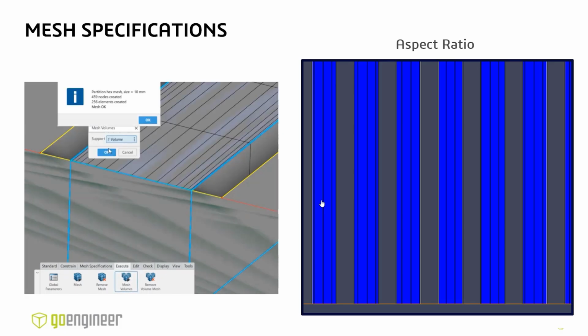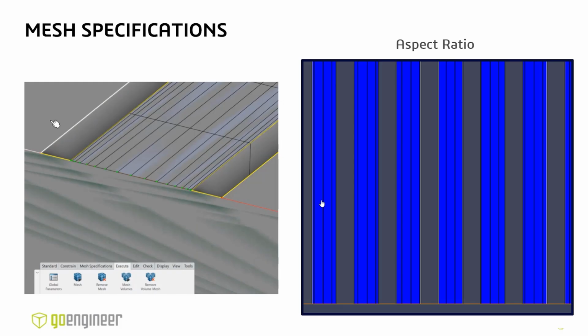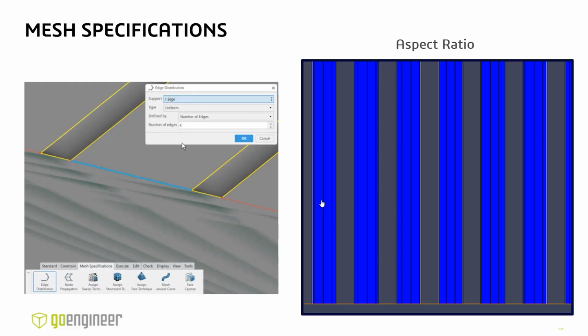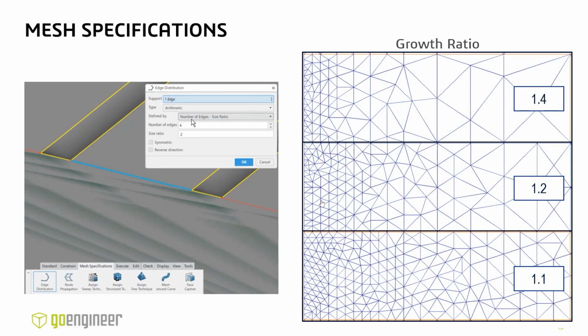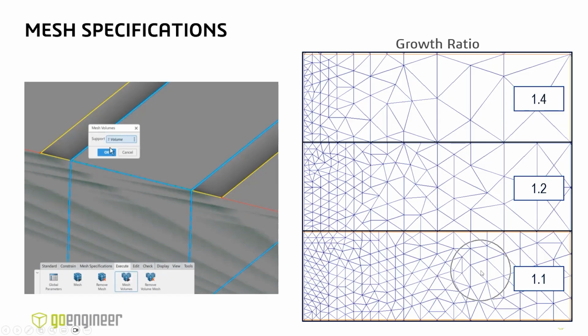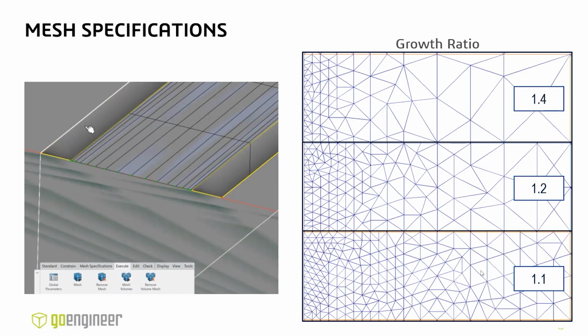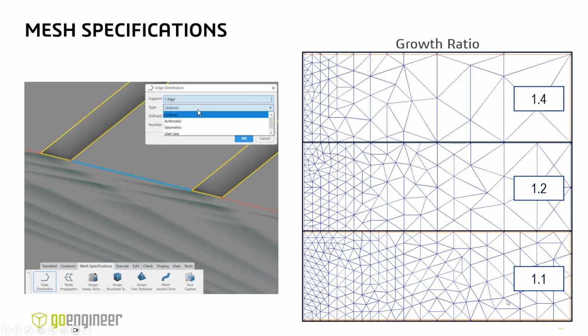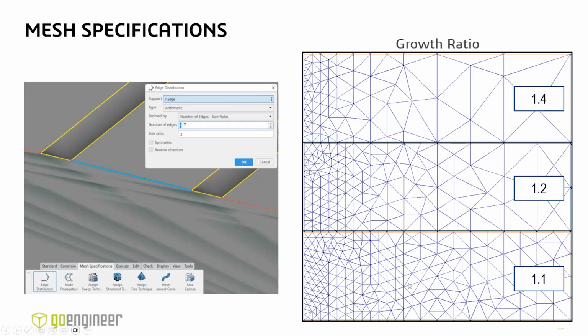I'm creating a mesh that looks a little bit like this. So you see that variation, thinner along the walls, thicker along the center, but I'm creating a lot of mesh cells. This idea of a growth ratio, it's in FEA, it's in CFD. The idea generally is the slower that you have that growth ratio, up here is faster, down here is slower. The slower I do that growth ratio, the more precise my results, the less error I'm introducing into the analysis. So a slow, steady growth is typically better.